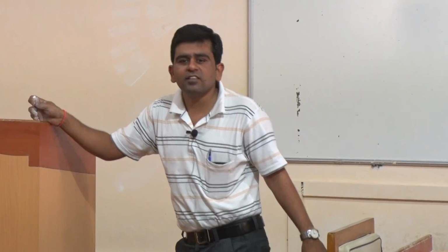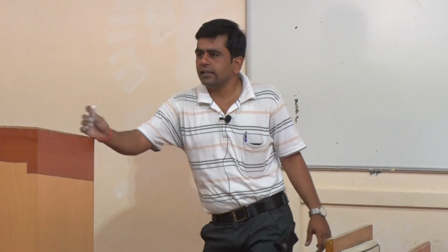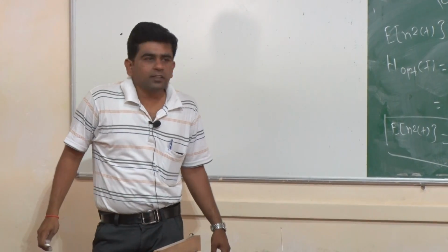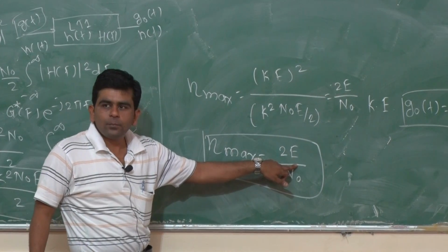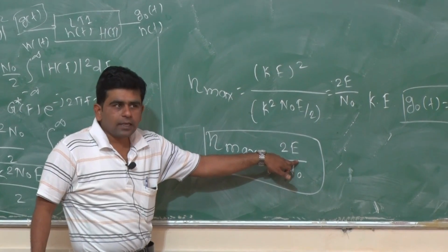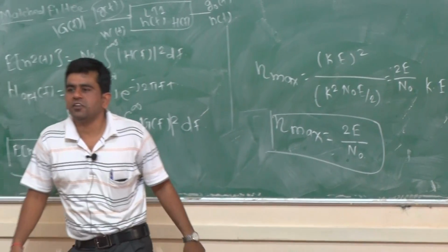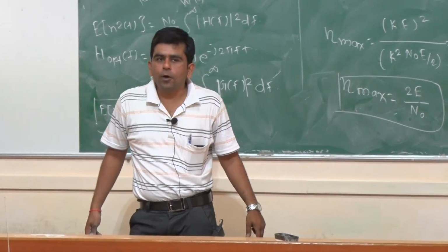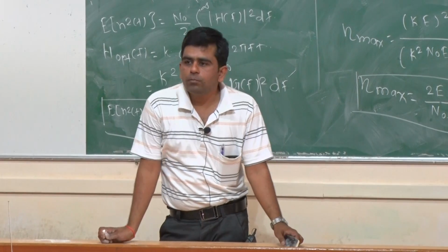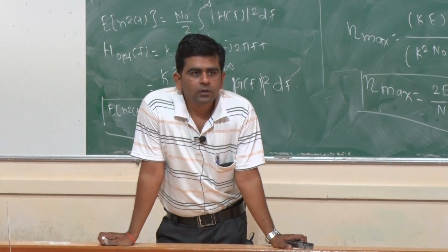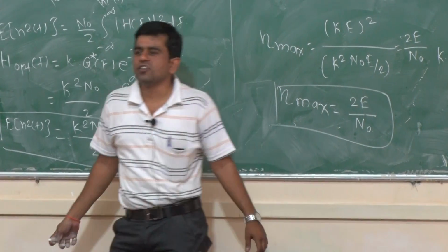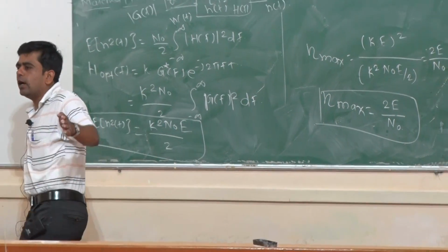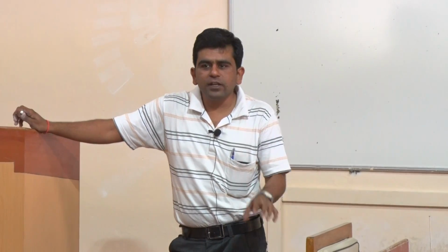From the property we can see that the peak signal to noise ratio is a function of energy associated with your signal g(t). Capital E is given as the integration from minus infinity to infinity of the magnitude spectrum |G(f)| squared df, and N_0 is the power spectral density of your white noise, which is the input to your filter. Actually we are using this matched filter.